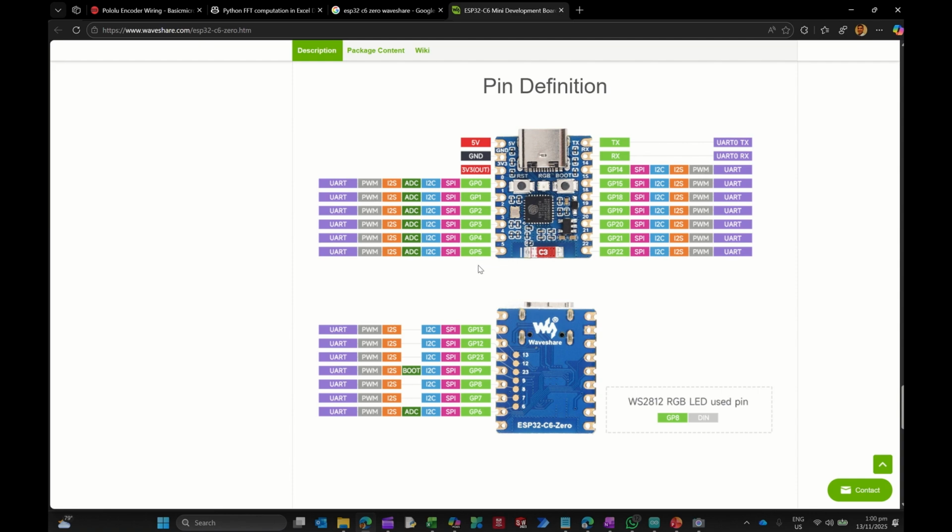So I'm using the PWM pin number 4 for PWM, and I'm toggling the gates to low and high to get the directionality of the motor between 2 and 3. And then essentially 22 is the one I'm actually sending the code for the encoder, right?